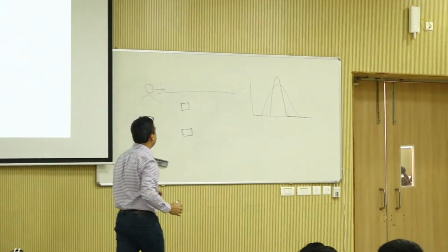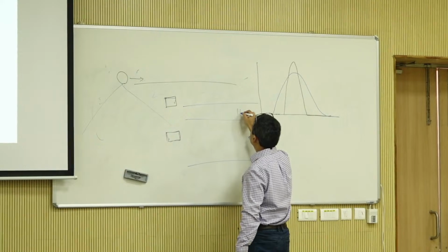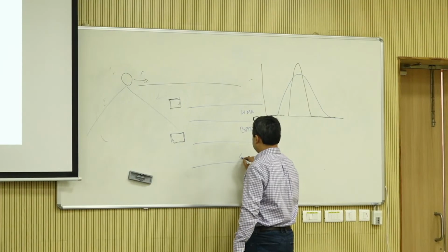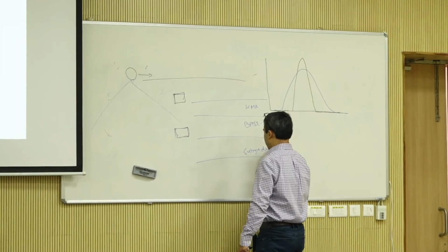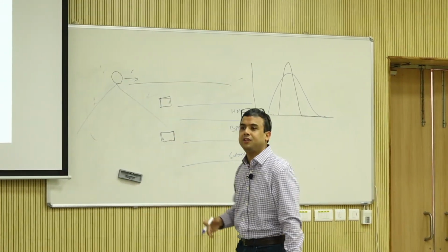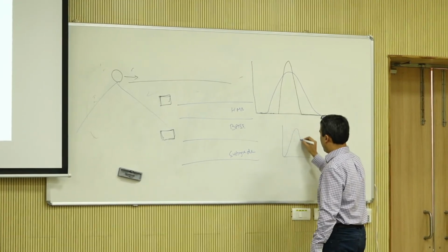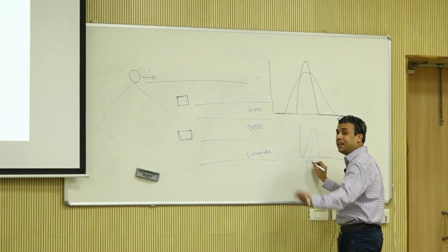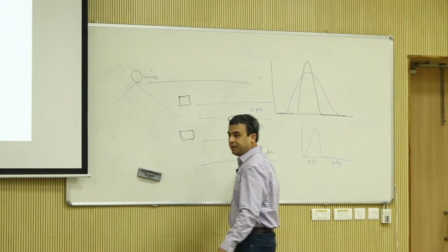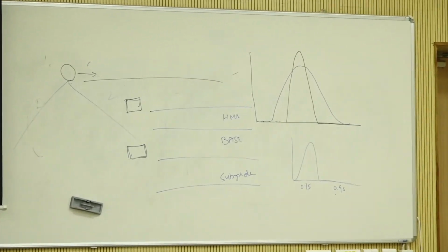Now the question is, you have a layer like this: HMA, base, subgrade. Somebody who knows resilient modulus testing, you have run it, right? What is the pulse and rest period? Do you remember? 0.1, 0.9, right? 0.1 second. We'll get to that. People who don't know, don't worry. 0.1, 0.9. Is that for base? Is that for subgrade? Is that for everything? Is it 2 inches below, 5 inches below, 6 inches below? Where is it?